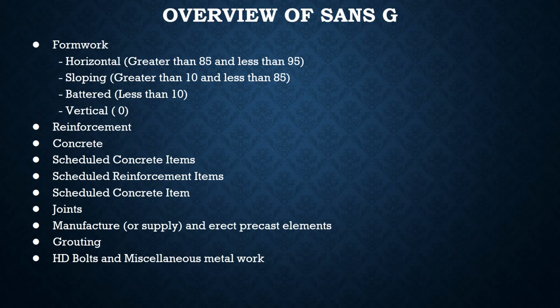This is measured in tons, however, it needs to state whether supplied by contractor or others, and the rate covers costs of supplying and delivering or taking delivery, fixing or casting in concrete, and all cleaning, preparation, and finishing.